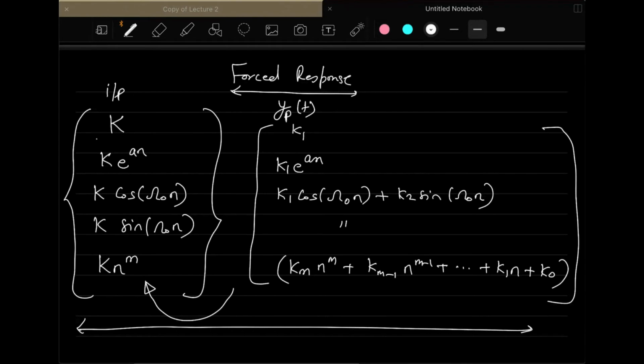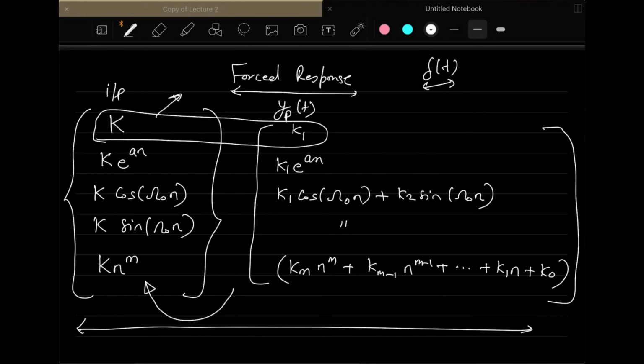So we took the derivative of the response that we got for the unit step, assuming that the derivative is a linear operator so that it can move inside the system. Based on that, you got the response for the impulse by taking the derivative of the unit step response.